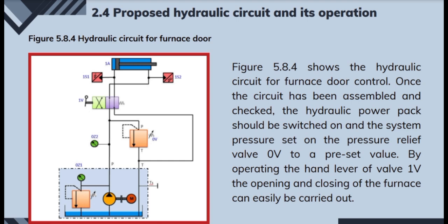Hydraulic power pump and motor, the red M. Its function is to convert electrical energy into hydraulic power. The electric motor drives the pump which moves hydraulic fluid from the reservoir into the system. Reservoir T, that T above the circle with the M, the one with a line. Its function is to store hydraulic fluid and provide the supply of hydraulic oil so the fluid can be recirculated.